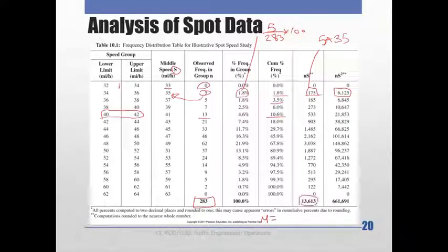So the mu in here is this guy, 13. And I think we mentioned that when we talked about statistical applications in traffic engineering. If we're using grouped data, you multiply the middle value times your frequencies, take the sigma of this, divided by n. So basically your n in here is 283. If you need to see the actual equation, go back to the statistical applications and traffic engineering notes. You will see the actual equations for these.